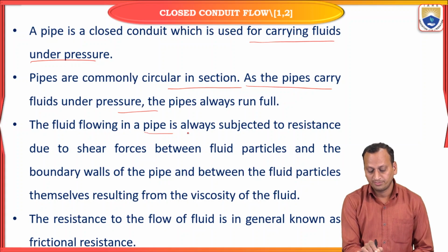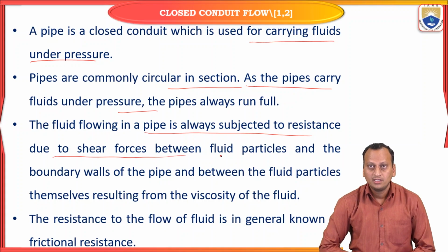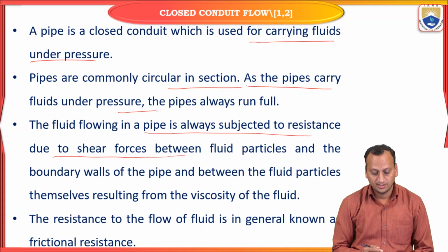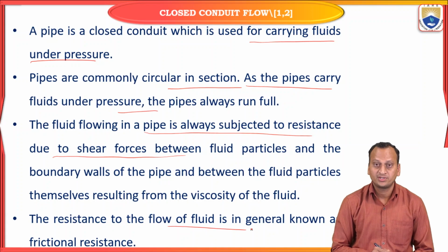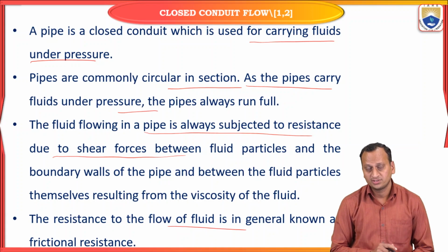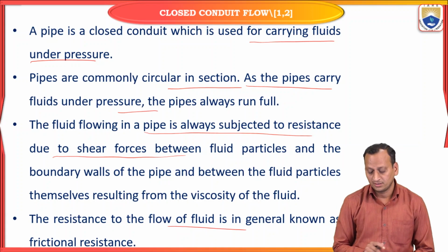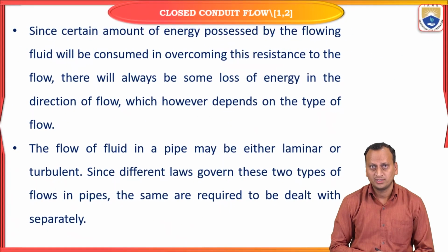The fluid flowing in a pipe is always subjected to a resistance due to shear forces between fluid particles and the boundary surface. This resistance to the flow of fluid is generally known as the frictional resistance. Due to this frictional resistance, a pressure drop takes place, since a certain amount of energy possessed by the flowing fluid is consumed in overcoming this resistance to the